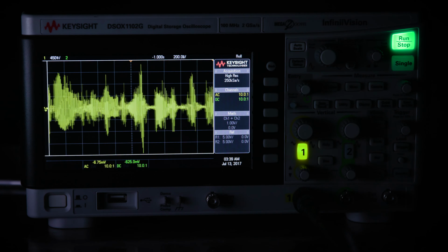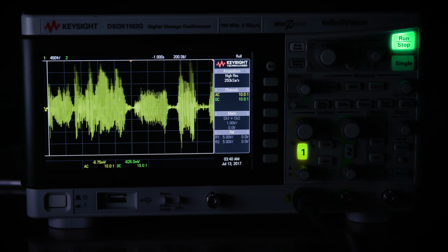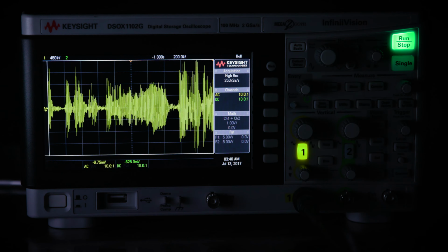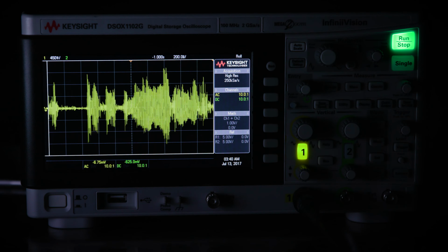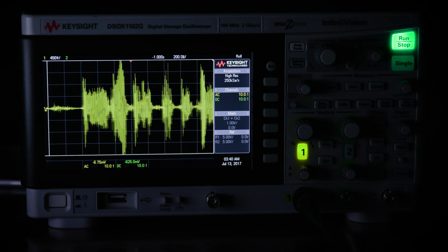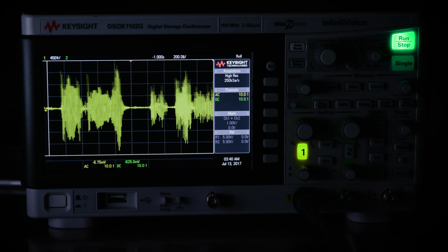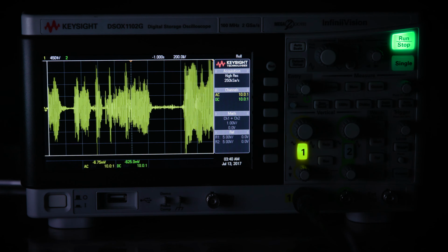And there's so much more. Beyond the noise floor, which dominates in oscilloscopes because they're so wide bandwidth, there's the SNR. I'm sorry, the SFDR: how far down are all your distortion products? Spurious free dynamic range. And so it's that combination of SFDR and SNR and bandwidth and flatness that really measures just how good an A to D converter is.